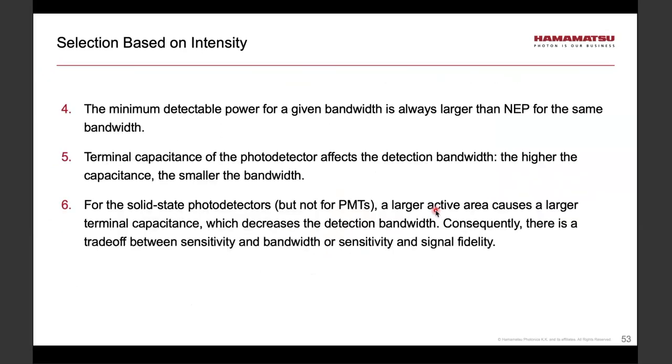Sometimes estimating signal to noise, sometimes estimating incident light power is difficult. I know of such situations myself from personal experience. Therefore, another approach is trial and error. One can simply try different photodetectors and empirically determine which one gives the best performance from this point of view.